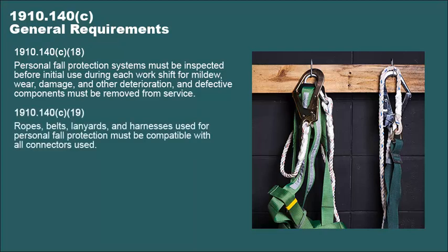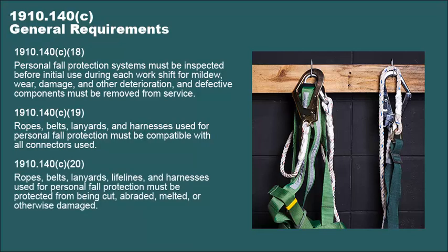All connectors should be compatible with ropes, belts, lanyards, and harnesses used for personal fall arrest systems. And personal fall protection systems such as ropes, belts, lanyards, lifelines, and harnesses must be protected from cuts, scrapes, melting, or damage in any other way.